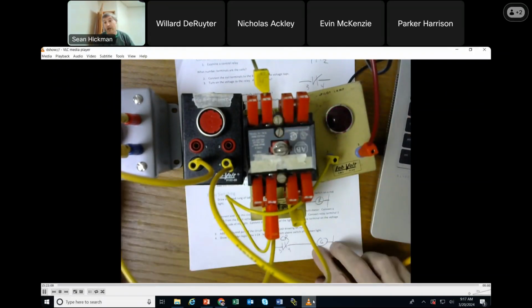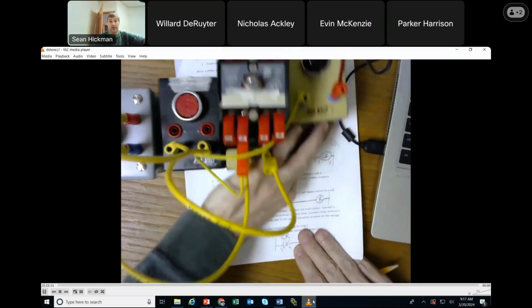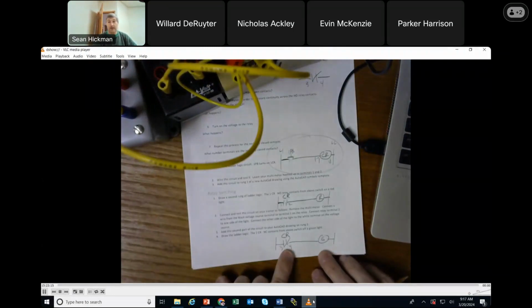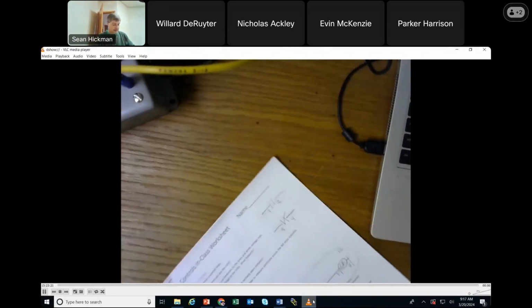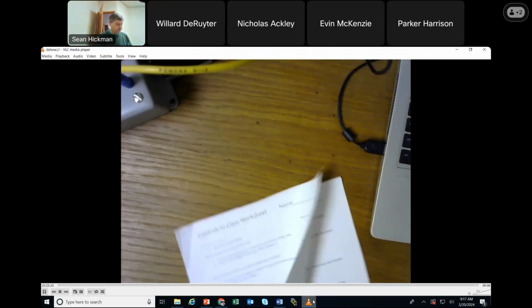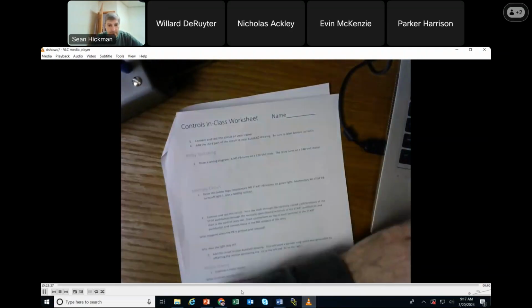How do you feel about the normally closed situation here with the relay? This second part here, scale of 1 to 10. Feeling good about a normally closed contact turning on the green light? Okay, and you could add it to the relay. All right. So let's see what else we got here.